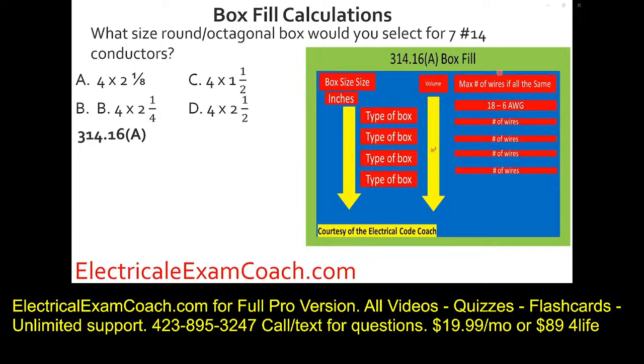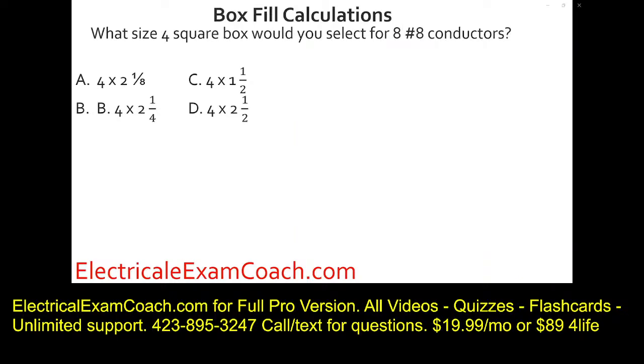We're going to start here on the right-hand side and we're going to find our gauge wire. Then we're going to come down and find a box that fits it, and be sure when we cross over that we stay in the right category of box, and we're going to select C. What size 4-square box would you select for 8 number 8 conductors?